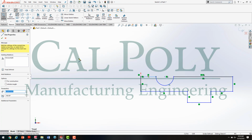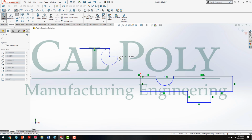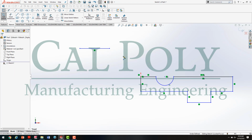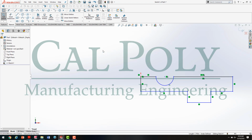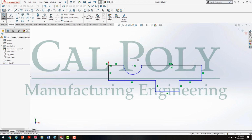So again, I'm going to show you that on the screen on the side right here. If I draw a straight line, click my mouse button, then flick my wrist, it'll automatically create an arc for you. I'm going to press escape. I'm going to highlight that line and hit delete to delete that line. So now I've got the overall profile drawn for my front view.